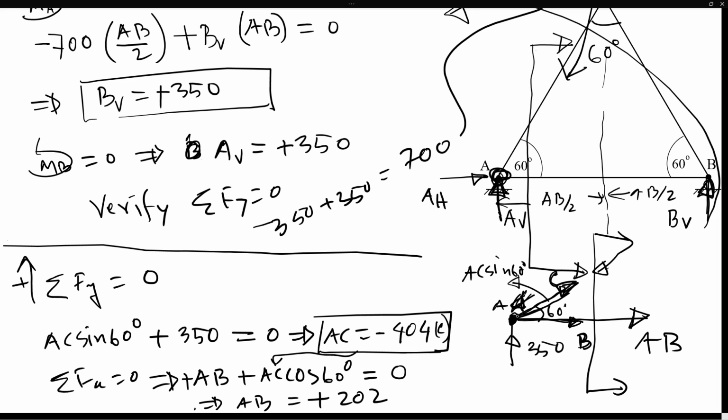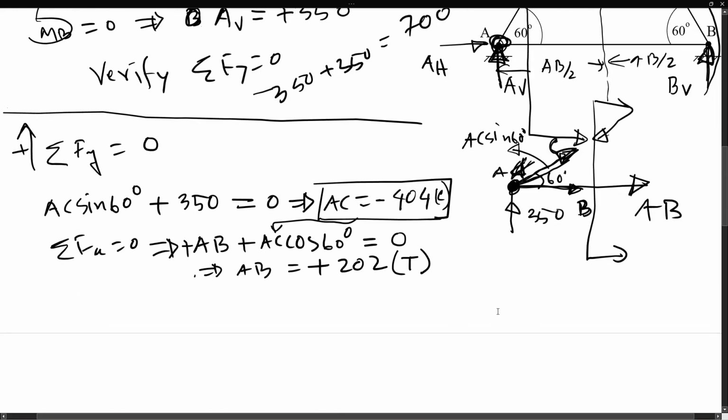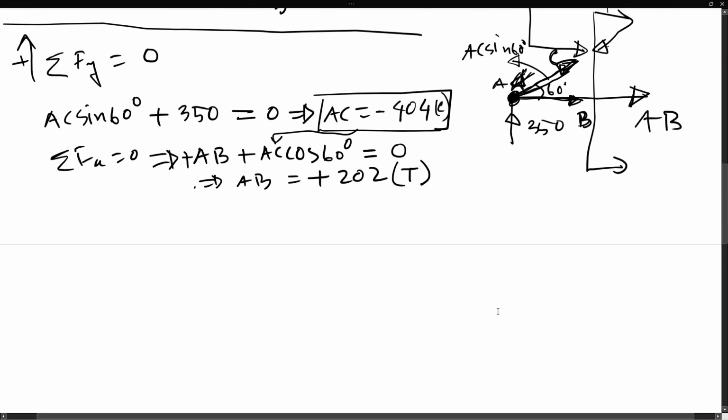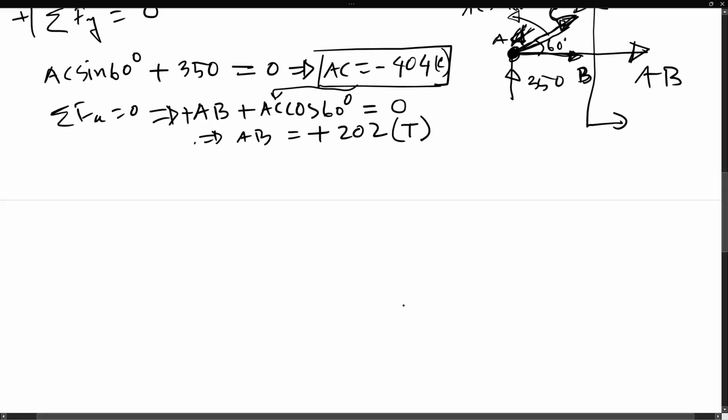So you're looking at point A, and this AB force is pulling that point. So if it's pulling, then it's in tension. So when you finish working all of these, finding all of the forces, you can do similarly, cut point, look at point B and find all these forces, and you have to finally redraw a triangle to complete the process.